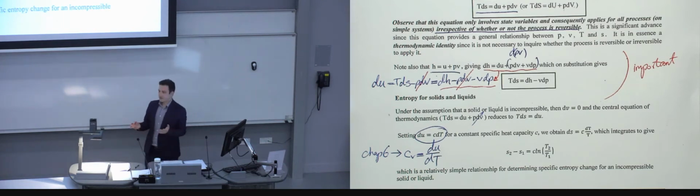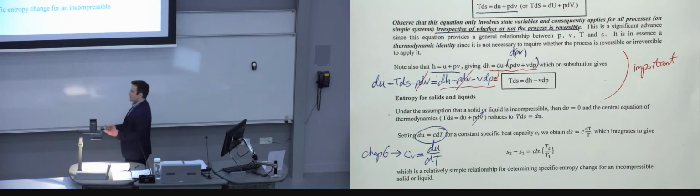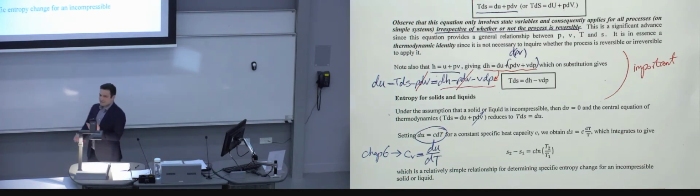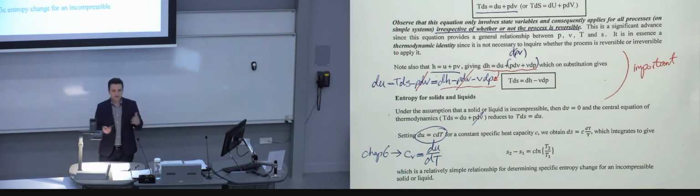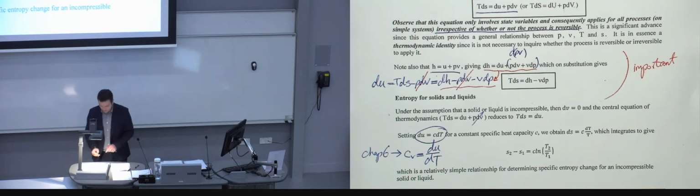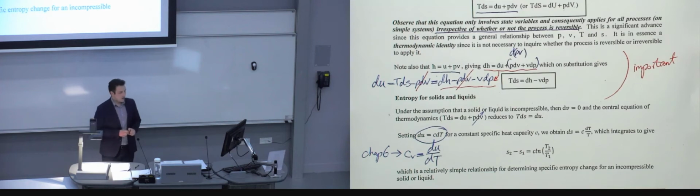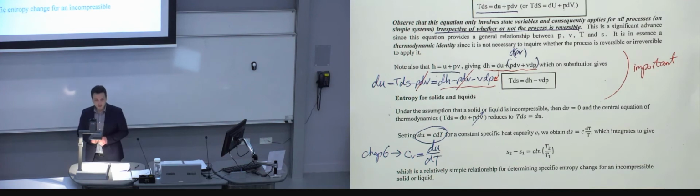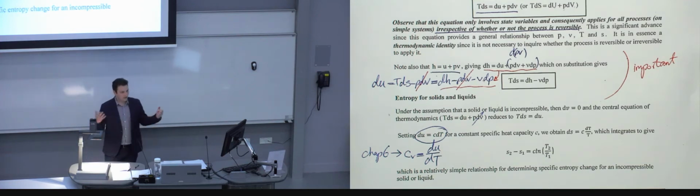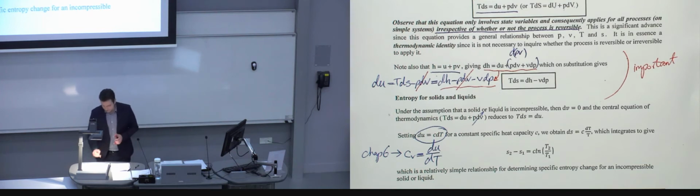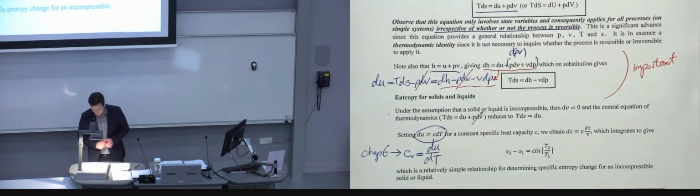Of course, if the volume is constant and the object is incompressible, Cv doesn't make any sense. But still the concept of the specific heat capacity is a physical quantity and therefore is relevant. And therefore that will be simplified to just a C. That's why you see in some equations you don't have Cp or Cv, you only see the quantity C, or a constant C. And that's because Cp and Cv only make sense when you're dealing with gases and compressibility and stuff like that. So that is that equation from there.